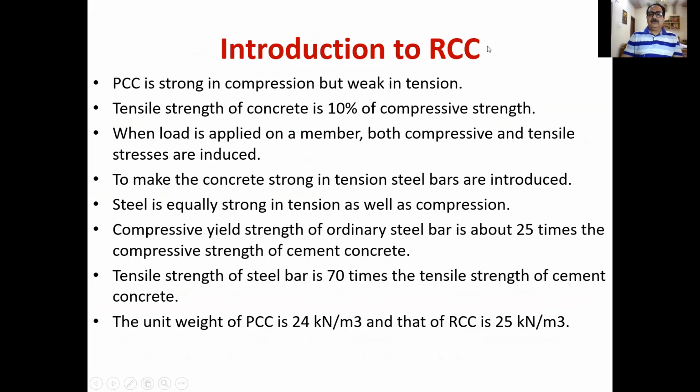Now, introduction to RCC. There are certain facts which we need to understand before going to the subject. PCC is strong in compression, but it is weak in tension. The tensile strength of concrete is only 10% of the compressive strength. So we can easily see from here, if the compressive strength is 20 Newton per mm square, only 10% will be the tensile strength. So it is very weak in tension.